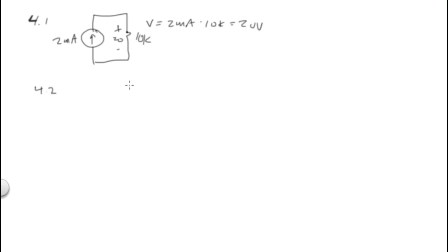So basically now we have a 3 milliamp source, and we have a pot, and we have a wiper that we can pick off a resistance at. So we have a 10K pot. If it's all the way to the bottom, it forces the current to go all the way through the 10K. If it's all the way at the top, there's no resistance.